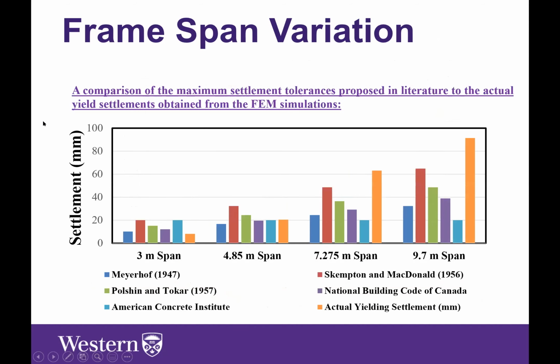And this is a comparison of our settlement tolerances to the actual yielding settlement obtained. And again, as we said before, the yielding settlement here is the settlement needed to produce a first crack, to throw you into the nonlinearity region.